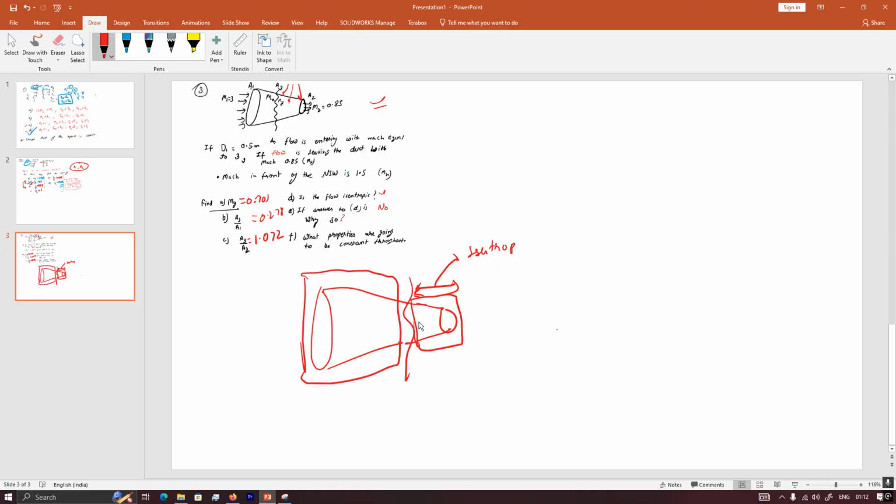So that's why we can use the A2 by A1 formula for this and this separately. We couldn't use the A3 by A1 by A2 thing directly. But using these two we can get that value. But that's the whole point. These two values are only valid for the part which is reversible and adiabatic, that is isentropic.